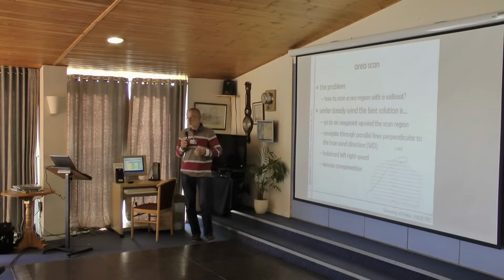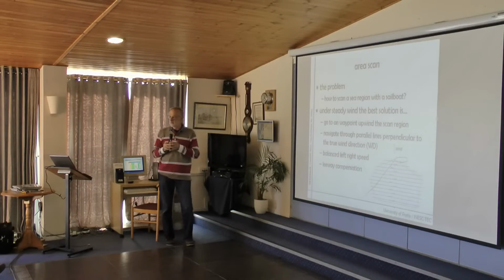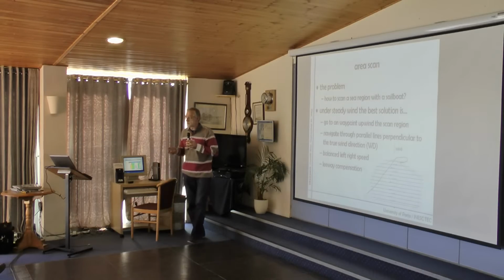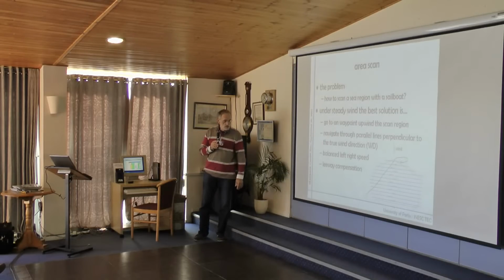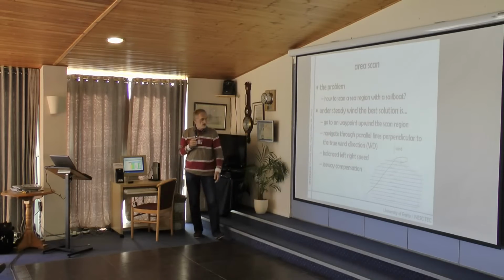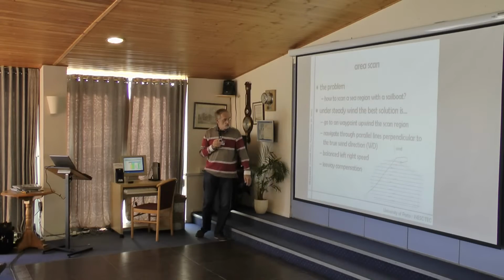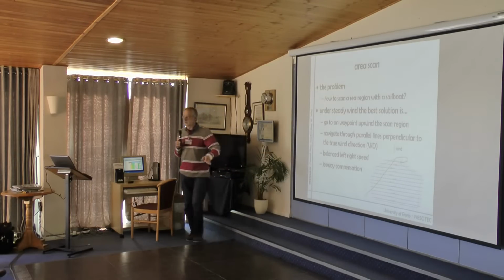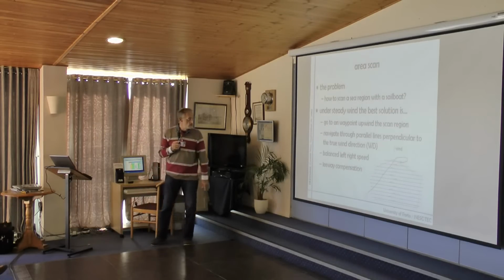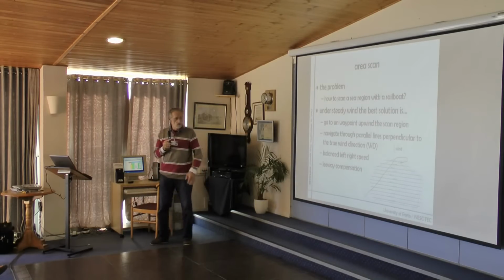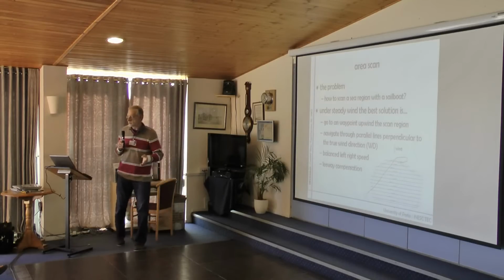And this is good because it will take the same rate, for example, of acquisition of data from the sea or from any parameter that the boat is going to acquire from the environment. And it is also the best course to compensate for the leeway, because you can go slightly upwind to compensate the natural leeway of the boat. I think everyone that sails agrees with this solution.